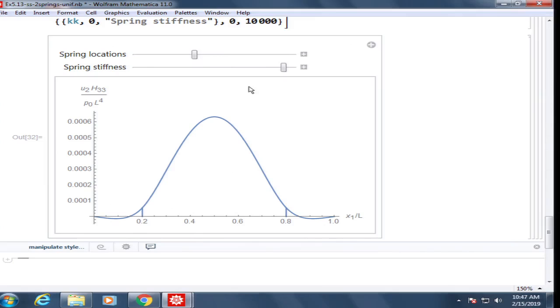You take all these terms on the right hand side, divided by k, so essentially you receive that U2 at alpha L is 0, right? Because the derivatives would always be very small already. So this equation would be equivalent to writing displacement 0 in that case. That's why you see that after increasing the spring stiffness by a huge margin, you don't see any displacement.